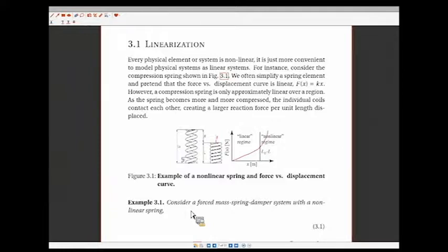So the thing to keep in mind is that it makes things easier, but it also makes your solution less accurate. It is an approximation, and it's based off the Taylor series. A Taylor series is a way in which you can take some sort of function and repose it as a polynomial, and if you carry out that polynomial to an infinite summation, it's perfect. In linearization, we're carrying out that polynomial to just the 0th term and the first term. So we're cutting off a lot of those terms in the Taylor series solution for some sort of signal.